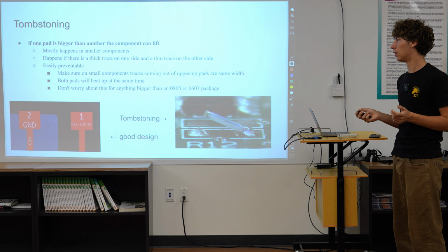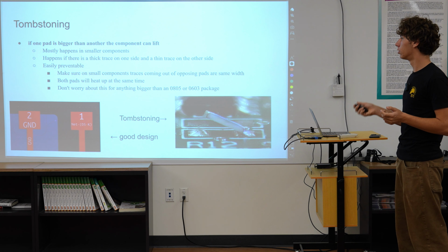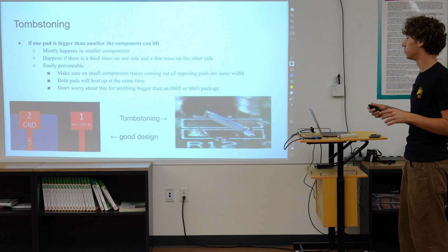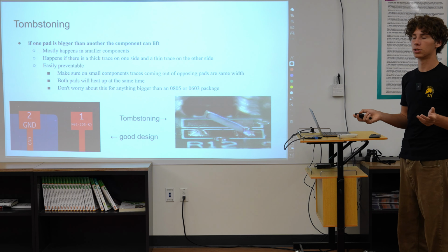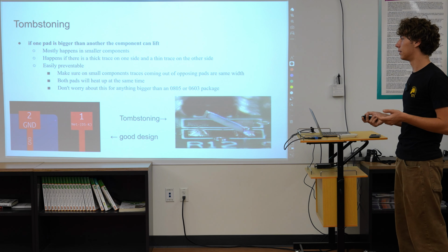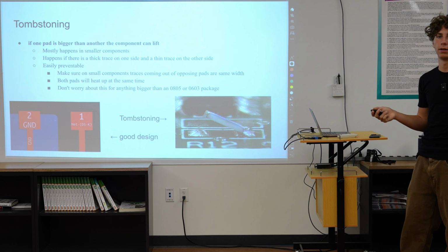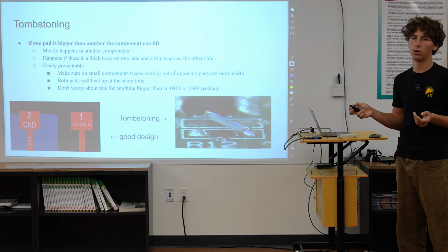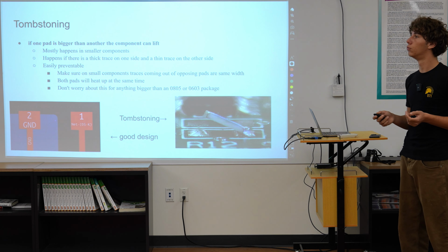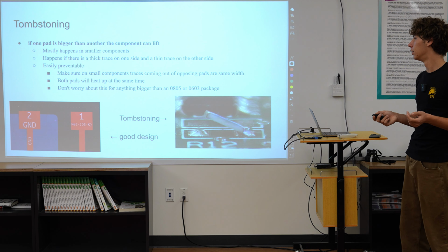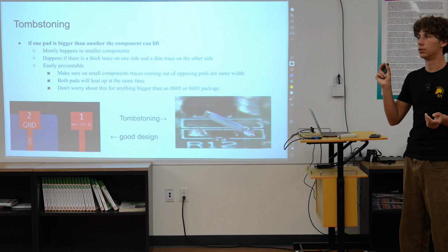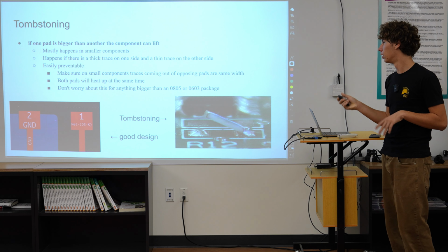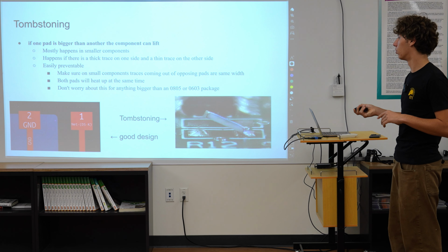And this is pretty easily preventable. If you make sure that on small components, traces coming out of opposing pads are the same width, then you're pretty much going to be good. Both pads will heat up at the same time, and then don't worry about this for anything bigger than 0805. That's the biggest I've seen tombstone. 1206 components maybe could, but definitely those big electrolytic capacitors, they have no way of tombstoning. This just happens because the components are so light.